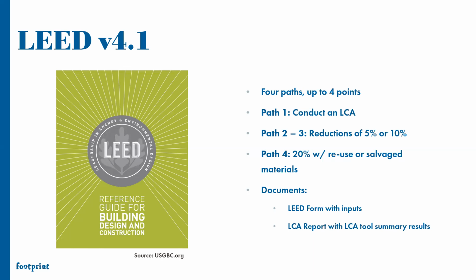So with LEED version 4, we talk about that same inclusion of your complete structural and architectural envelope. There are those same exclusions where you won't be including interior partitions, and you won't be including site excavation or building services. If there's a parkade, absolutely you would include it, but you wouldn't include any site parking or ground level site parking. But really, you're taking a look at your architectural and structural drawings and trying to see where the different reductions are possible.